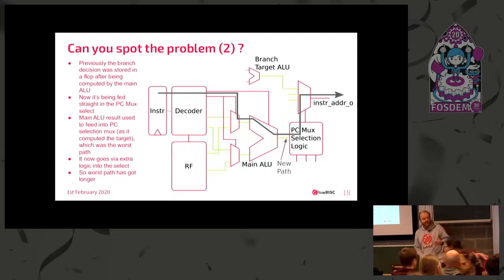So what's happening here, for people who aren't familiar with synthesis and logic implementation, the thing that sets the maximum frequency in your design is based around the length of the longest chain of logic in your design. So you have a whole bunch of logic gates all connected together, and the longer those chains get, the longer it takes for a signal to propagate down and the slower your clock can run.